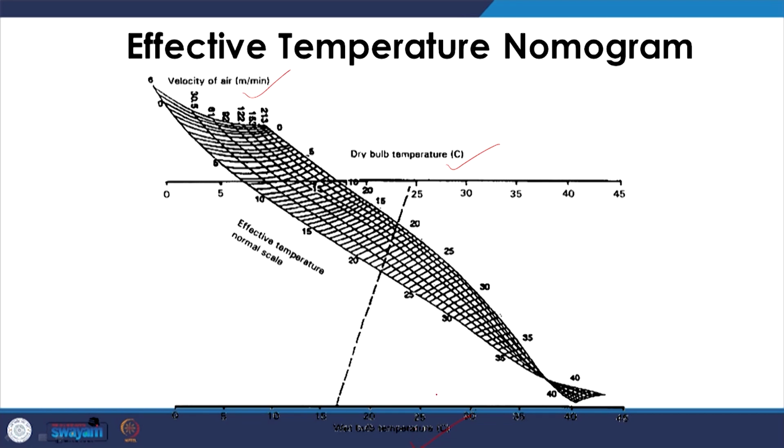Wet bulb temperature is always lower than the dry bulb temperature by virtue of the humidity present in the air. It combined these 3 quantities into a quantity called effective temperature, so if we knew them, we would know at what range of effective temperature people would feel comfortable.